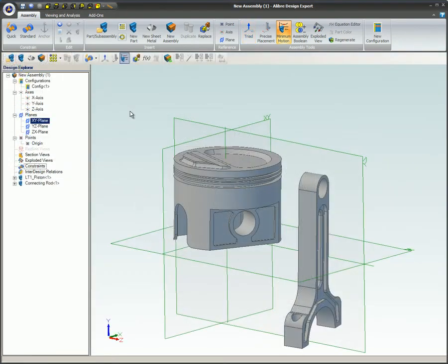The Triad tool. Select the Triad tool from the Assembly Modeling toolbar or from the Assembly tools on the ribbon. Select the part or subassembly, and the Triad tool will be displayed on the part. There will be 3 linear arrows and 3 rotation rings. One of the arrows will be yellow. The arrow or rotation ring that is yellow will be the only direction in which the part can be moved